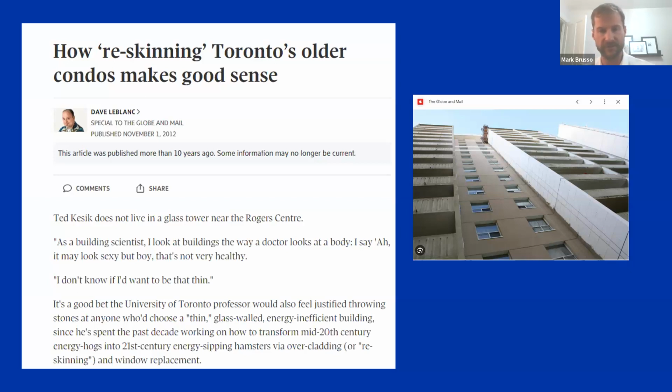There wasn't an option to move people out of the building and start removing walls and studying from the inside. So what happened, and what is continuing to happen, is a solution going forward of cladding this with a type of rain screen system, and that was with an EIFS. Personally, EIFS, in my opinion, is not one of my favorite types of finishes on a building. It is extruded polystyrene with a finish coat with a drainage plane.